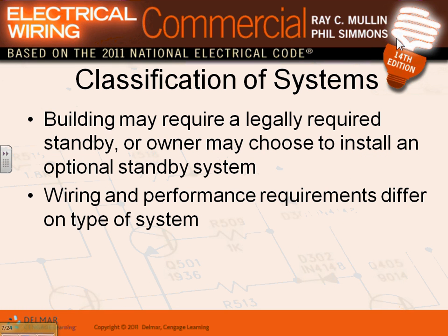A building may require a legally required standby system. Now, who classifies that every commercial or industrial building that is open to the public needs an emergency system? That's by the building code and the 101 Life Safety Code. But which one needs a standby system and which one needs legally required? Legally required is usually decided by a government, state, federal, or local, that certain loads need to be legally required.